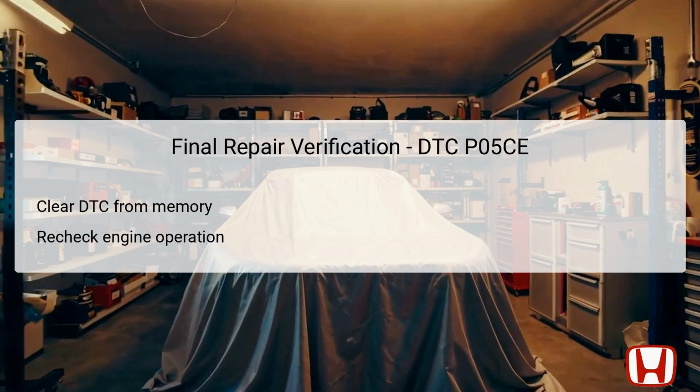After the necessary repairs and replacements have been conducted regarding DTC P05CE, it is essential to perform a final verification of the repairs. This begins with clearing the DTC from the PCM's memory using the HDS. Clearing the code resets the monitoring system and allows it to reevaluate the conditions of the engine components previously implicated.